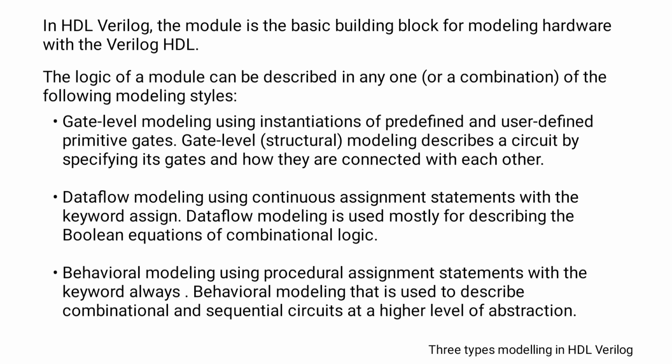The third modeling is behavioral modeling, using procedural assignment statements with the keyword always. If any Verilog module or Verilog program has the always keyword, then that program belongs to behavioral modeling. Behavioral modeling is used to describe combinational and sequential circuits at a higher level of abstraction. So out of 3, the first 2 are used for combinational; the third one also can be used for combinational, but for sequential we strictly use behavioral modeling.